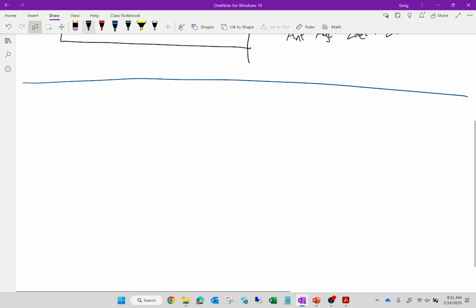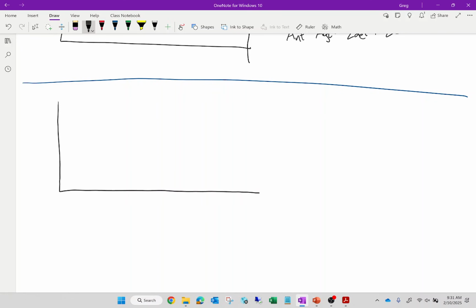I'm going to draw a really exaggerated angle, but you'll see what I'm doing. Is it clear from my picture, this is the long leg, this is the short leg? The centroid of this angle is about right there. What is X bar for shear lag? It is the distance from the connected face to the centroid. So the question is, which face is connected?